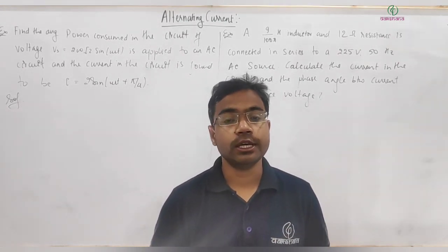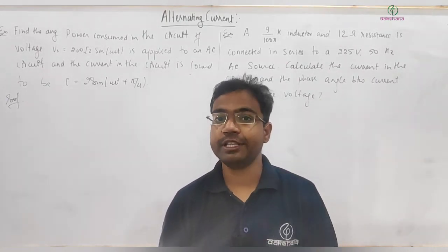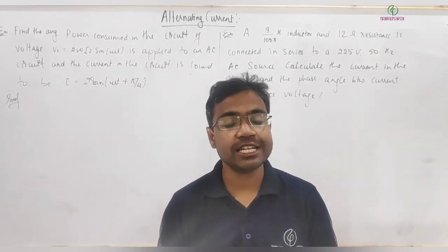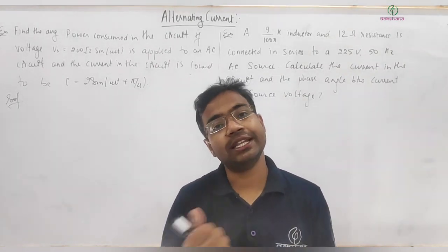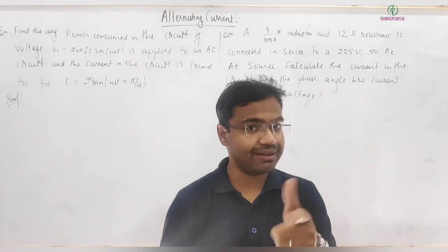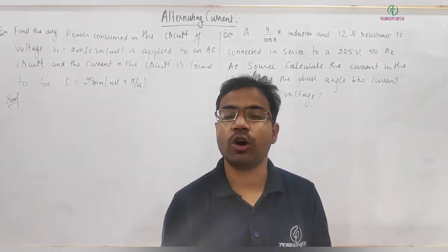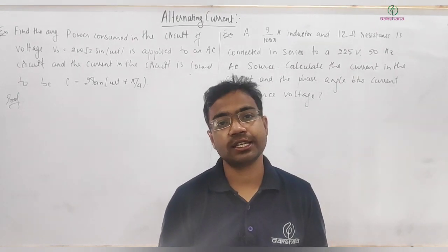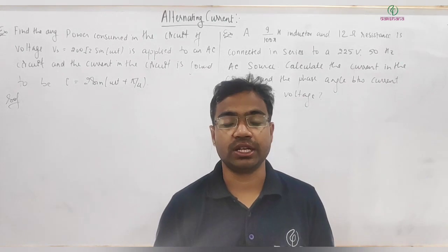You can simply imagine, if there is no resistor present in the circuit, then the average power will be 0. But instantaneous power is also involved, in the sense that it is stored and then released in inductors and capacitors. Remember, instantaneous power is normally not asked. If it is asked, you need to deal with it in a different way.